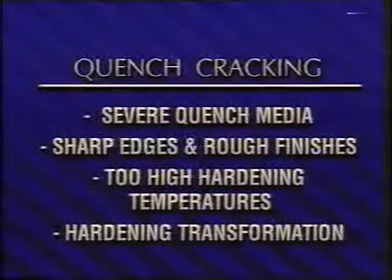Unless special precautions are taken when heating to high temperatures in an oxidizing atmosphere, the risk of losing carbon from the surface of steel is always present. Steels with severely decarburized surfaces show a marked reduction in fatigue strength.